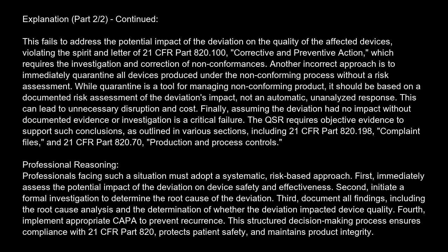Another incorrect approach is to immediately quarantine all devices produced under the nonconforming process without a risk assessment. While quarantine is a tool for managing nonconforming product, it should be based on a documented risk assessment of the deviation's impact, not an automatic, unanalyzed response. This can lead to unnecessary disruption and cost.